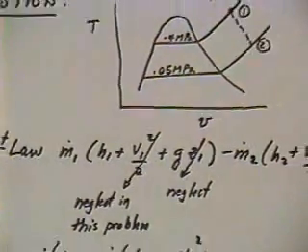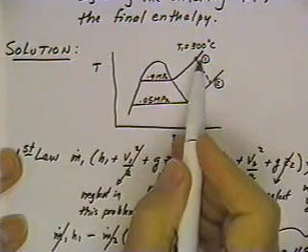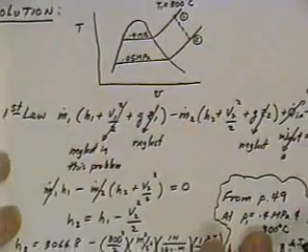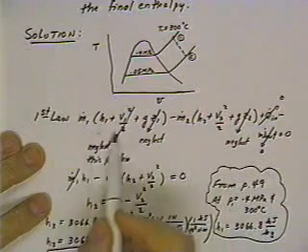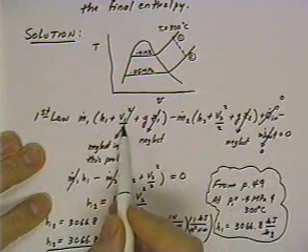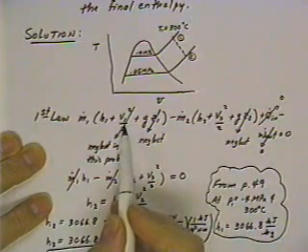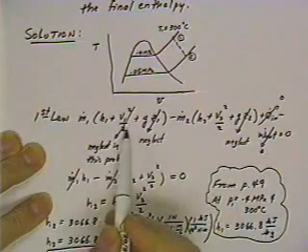Okay, so we can go back to our little graph here. We know that we are at 0.4 of a megapascal. We just calculated the enthalpy here. Let's go to our first law equation. First law equation, then, we're throwing out entering kinetic energy. Now this term would not necessarily be thrown out in all cases, but we're given that the entering kinetic energy is small compared to the leaving, so therefore we can neglect that.